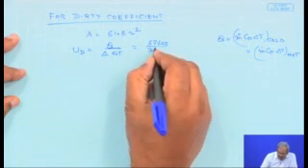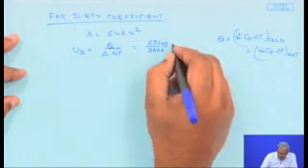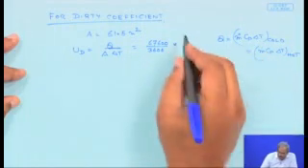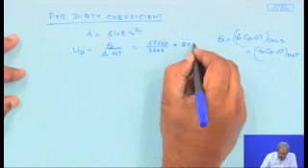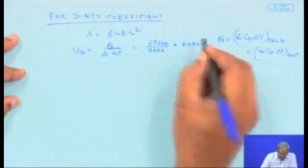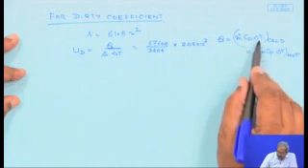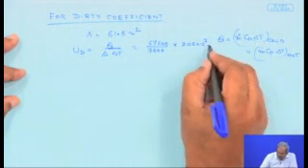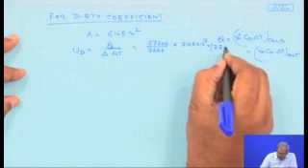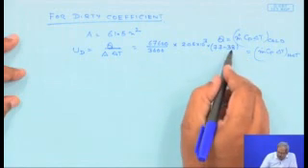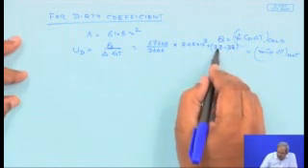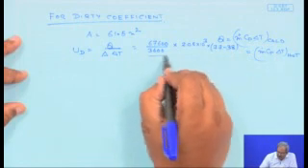67,600 by 3600, Cp for the cold side 2.05 into 10 to the power 3, and delta T, that is the temperature rise of the cold side, which would be 77 minus 38. So from 38 the cold side fluid temperature has risen to 77.